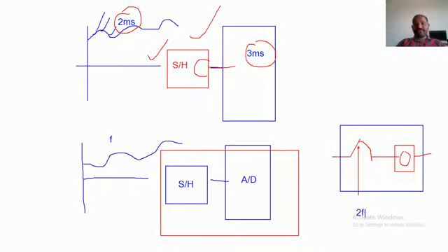So it means it will open and close this particular switch with a frequency of 2f, or in time period, we call it 1 by 2f. It is twice the input signal frequency. With that rate, the switch should open and close. Then only whatever variations are there at the input of the sample and hold circuit will be sampled perfectly by the circuit, and converted perfectly by the analog to digital converter into digital format.